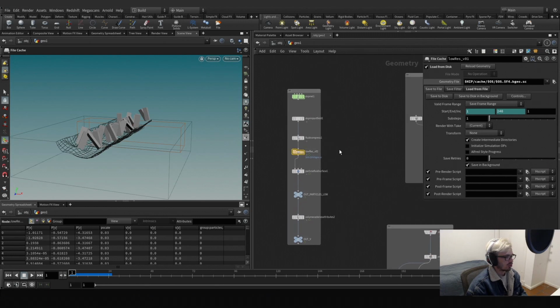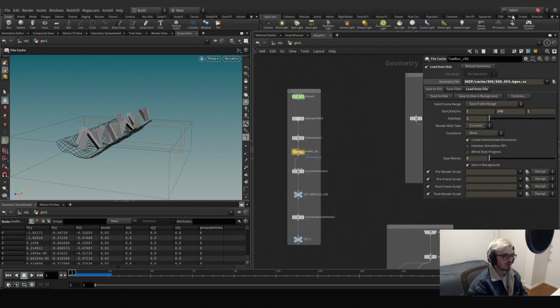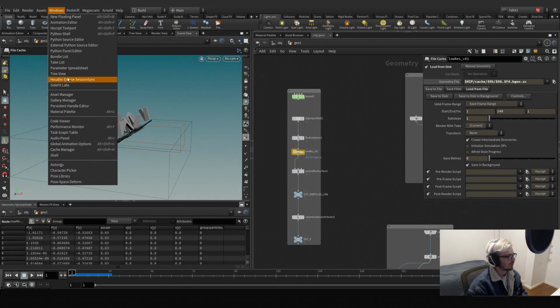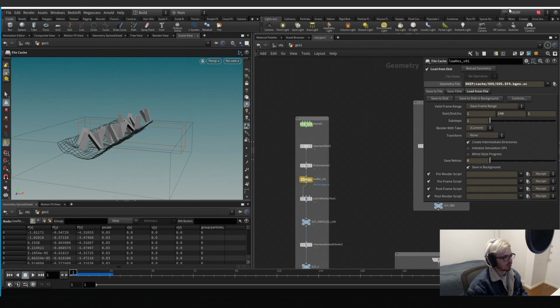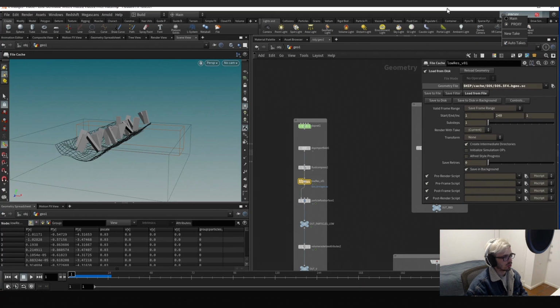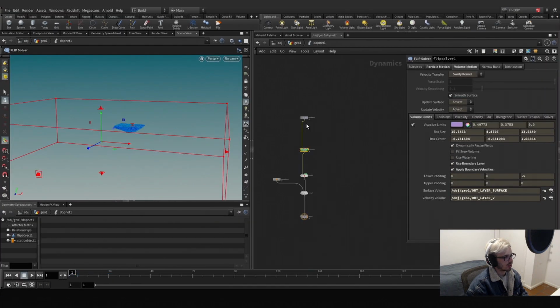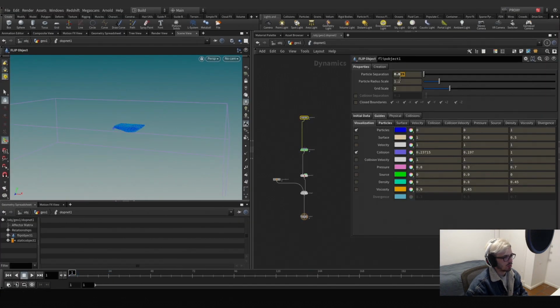geometry here. So before fixing this, we're going to make a new take. This take will be called, if we go to Windows and Take List, it will be called proxy. Inside the proxy here, we are going to allow new takes. We're going to hop in and move this to 0.5. This will make everything faster.